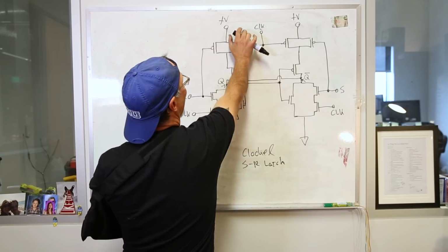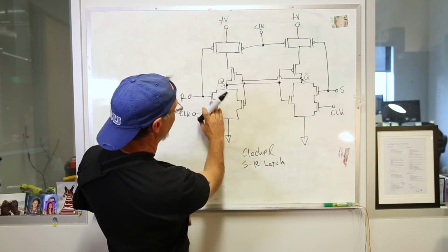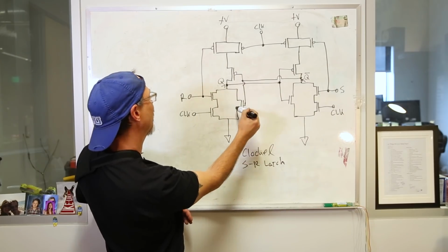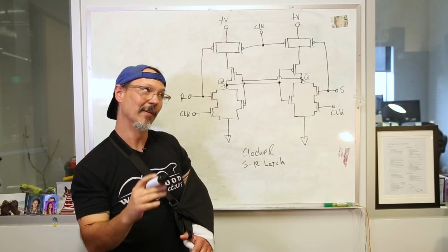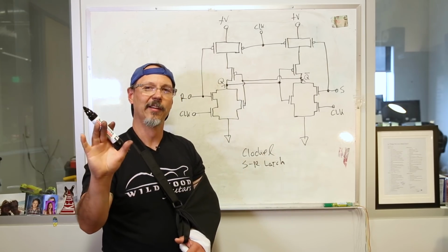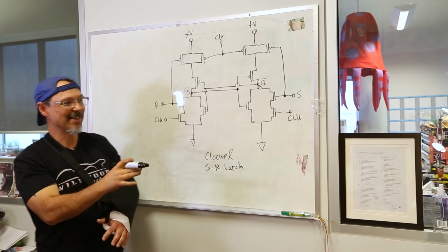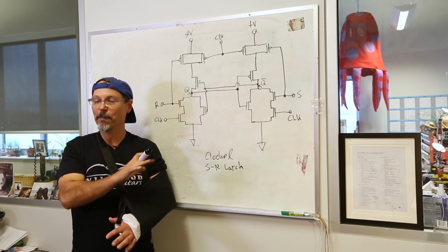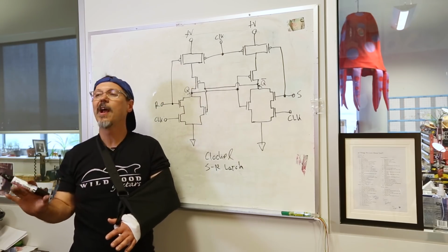You can see, if you take that guy out, you've got these guys at the top, and you take this guy out, you've got these two parallel to each other. Now, to describe its functionality, first, I promise you it's going to work just like the regular flip-flop does, only clocked. What the clock does, basically, is disable the thing until the clock is high. And so things can only happen when the clock is high.